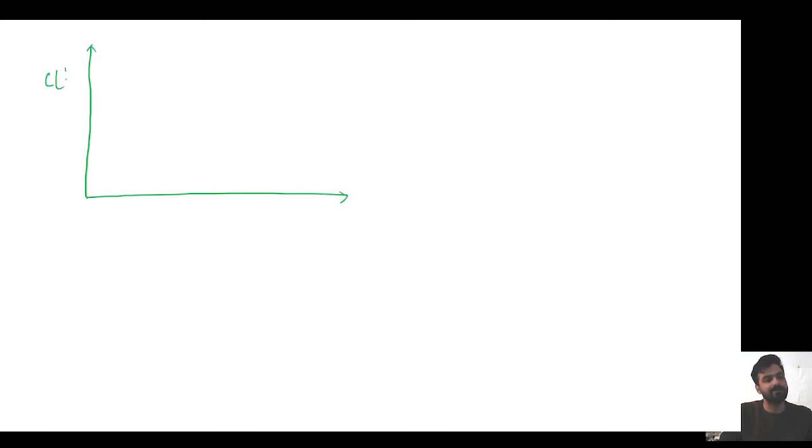If here it is Ct and here it is time, the plot will vary in this way. It will be 0 initially, it will go to a maximum, and again it will come to 0. Are you getting? So this is the concentration versus time curve for n CSTRs in series. Okay. Now when we talk about, my dear student, Et,